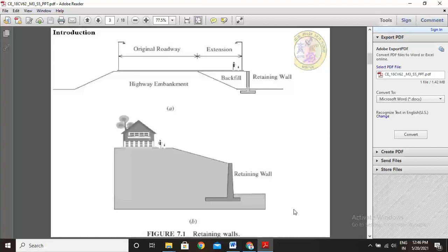Pressure is most important here. To minimize, avoid, protect or retain the pressure, on the left side and right side a retaining wall is constructed to resist the lateral earth pressure in terms of active earth pressure, passive earth pressure or pressure at rest.